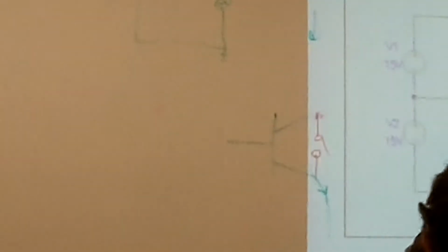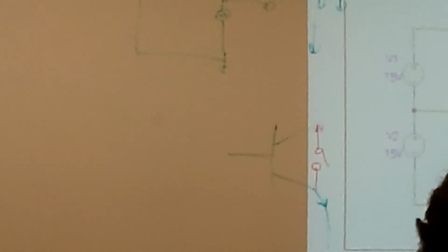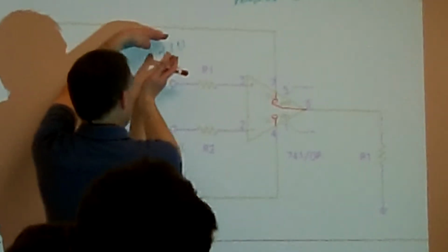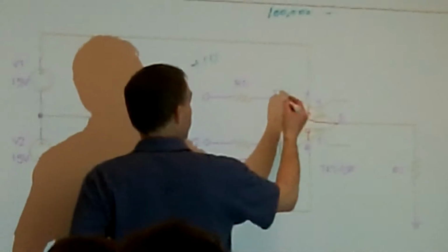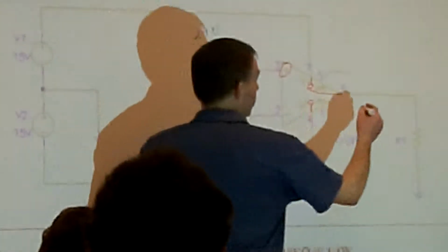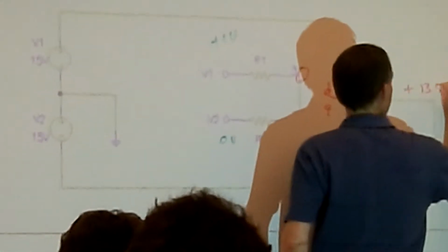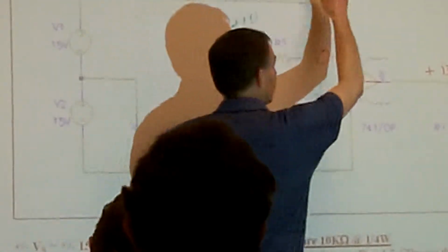When we're looking at the op amp, here's my output. The only difference is that here I have two choices. So, for example, if I have 1 volt on V1 and 0 volts on V2, we know that V1 is going to be more positive. It's on my non-inverting input, so my output is going to go to my positive 13.5 volts. So basically, since it's an open loop comparator, it's basically a switch.